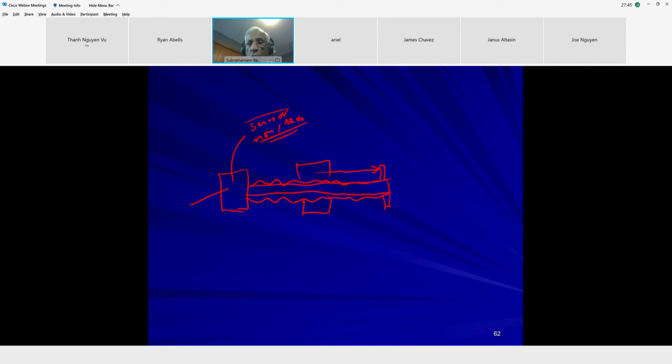So you can quit the motor and make the carriage stop here. Then when you reverse the direction of voltage to the motor, the carriage will go this way and will hit the end stop. It can't go anywhere beyond. And then you either visually or by some other means switch off the power. If you don't switch off the power, the motor is going to see what's called a stalling torque. Stalling torque is when current is applied to the motor, but it cannot spin because it's been stopped by a hard stop. So once it hits the stalling torque, depending on your voltage, the motor will act as a resistor, developing heat, and eventually will burn. So it is up to you to stop it quick.